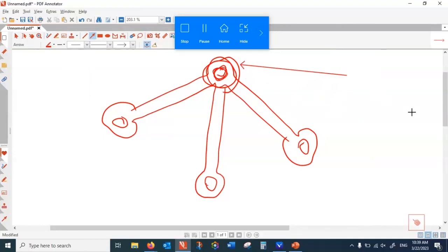when you apply a force at the pin, it would distribute the load, and each individual member can only take the force axially, right? So imagine this is a channel with a water. So the water comes at a junction, and the junction distributes water only axially. So it is wrong if you apply the force here. It is wrong if you apply the force anywhere but at the pin, because what it does is it starts to bend the member, and the minute it starts to bend, it is not a two-force member anymore.